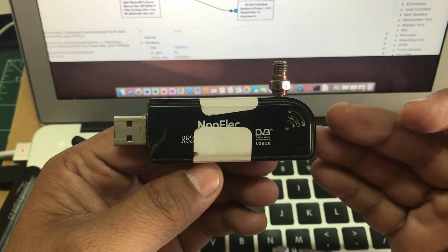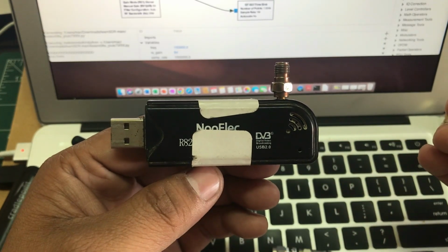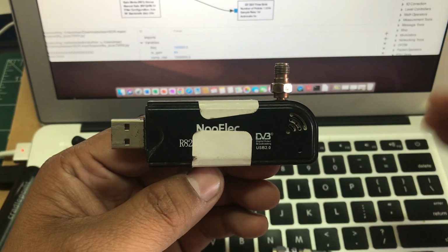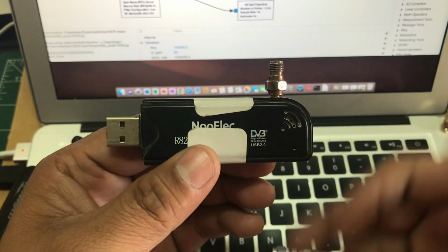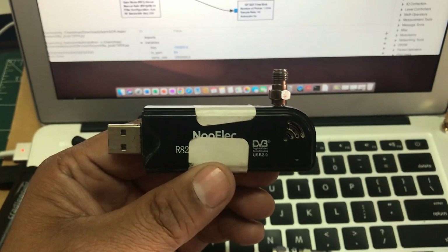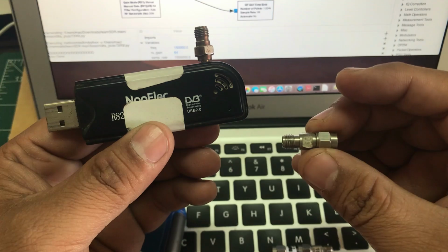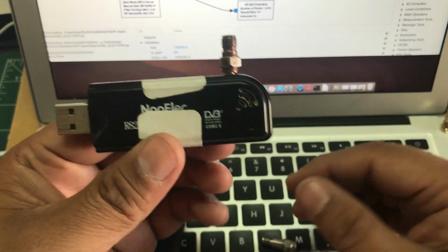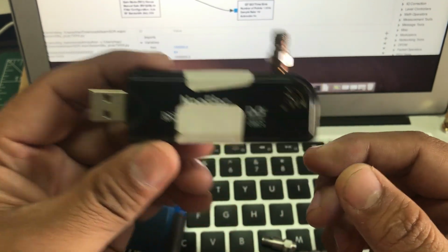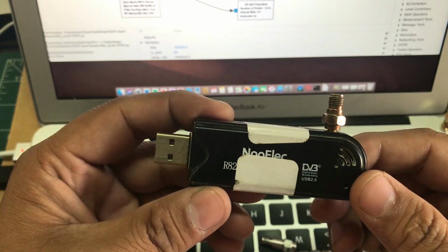I'll try to first receive the signal and find out what the baseline is, what it is without the attenuator. Then I'm going to mount my attenuator again, and I'm going to see how much my signal went down with the help of one of these, so we can see the functionality. So, a cheapest way of checking to see if your attenuators are properly working.